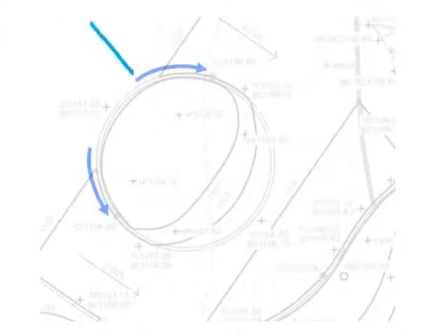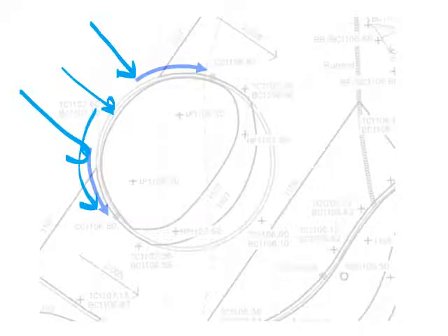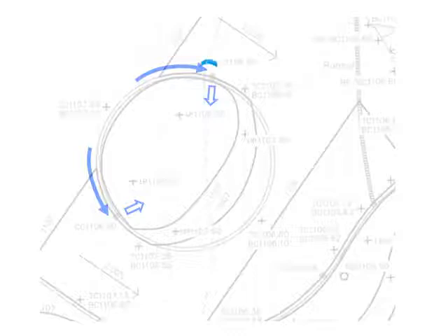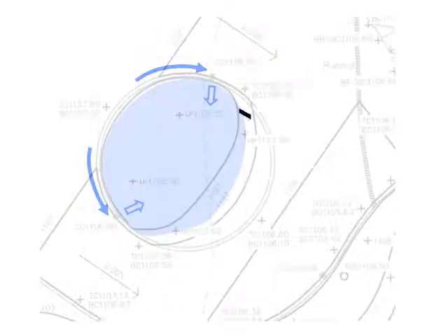So again, we have water coming down and hitting the system, and after it does that, it's going to flow around the edge of the curb until it finds an opening. Once it finds that opening, it's going to go into the system. That opening is going to consist of curb cuts. In this case, we have 2 curb cuts, and note that the elevation of those curb cuts have to be exactly the same. The system is going to fill up, of course, until it hits the berm that you have created inside your turnaround area.